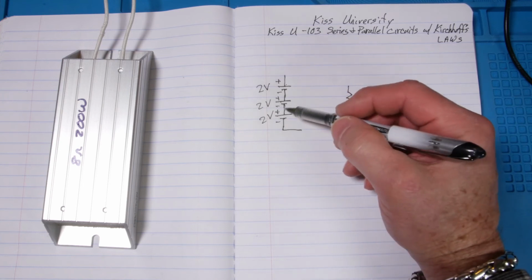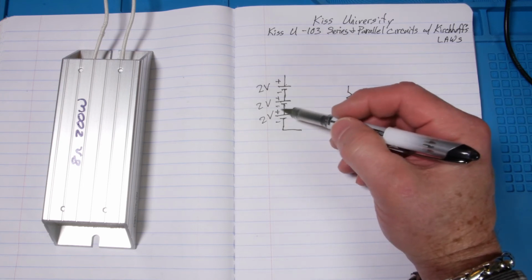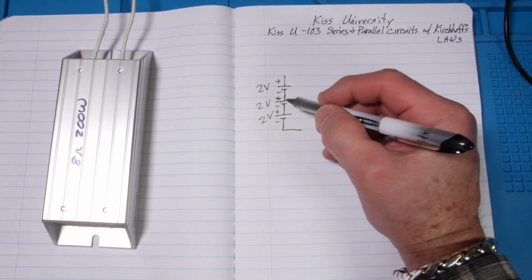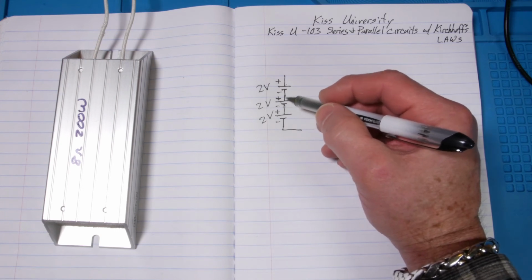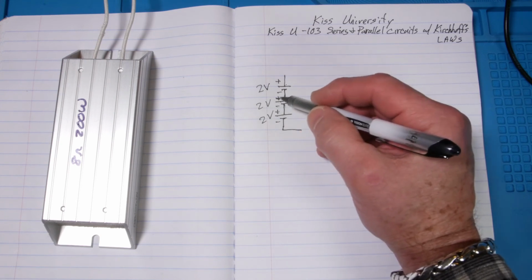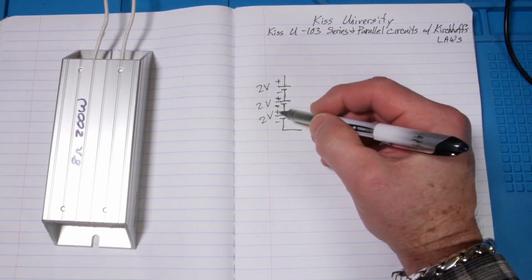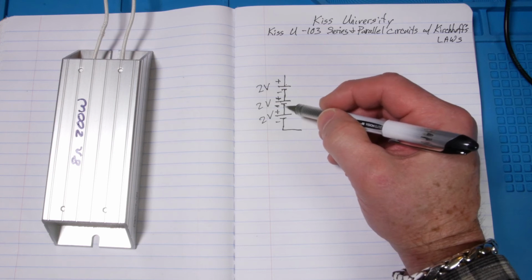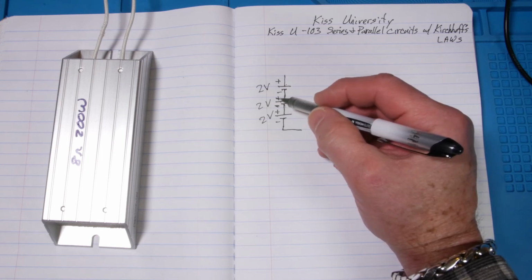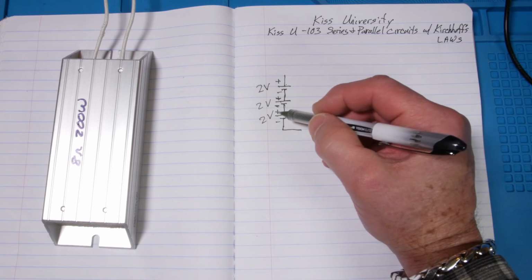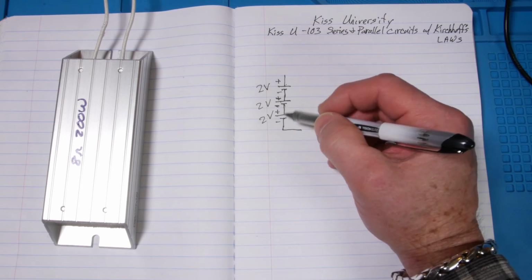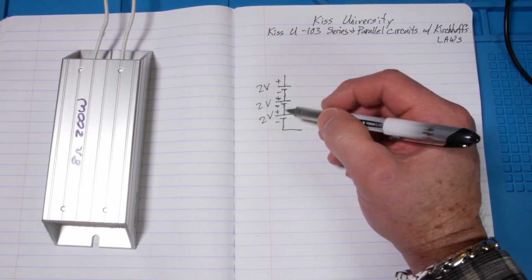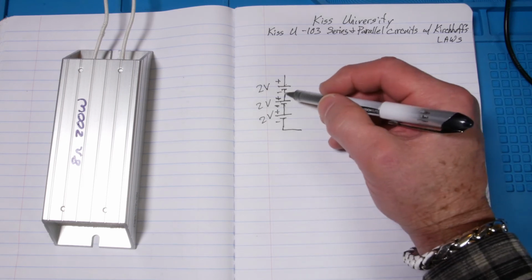Now this is a good example of how this plus and minus have nothing to do with each other. This minus has to do with this, because this is a potential difference between these 2 plates. This is voltage here, and it's plus to minus. This minus has nothing to do with the polarity of whatever this piece of wire is. Okay, it's negative in comparison to this, but compared to this one, it's not. It's the same potential. It's the same voltage on this plate and this plate, right there. It's all the same thing. There's nothing in between them. They're just connected together. Same here.